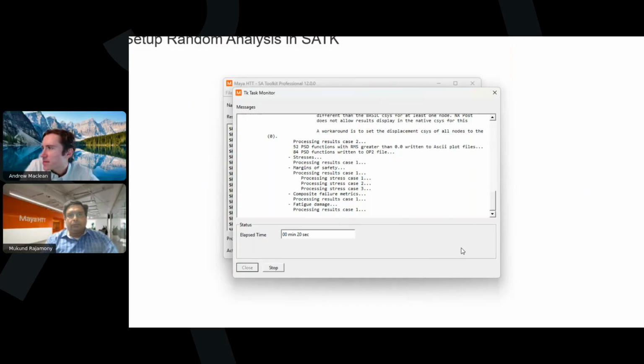I think it depends a bit, because ideally you would want to have your modes going well above the highest excitation frequency, but on a lot of models that may not be possible. So it does depend a bit. I think there's also both the question of having enough modes and also having enough effective mass. So it's a bit of a case by case.